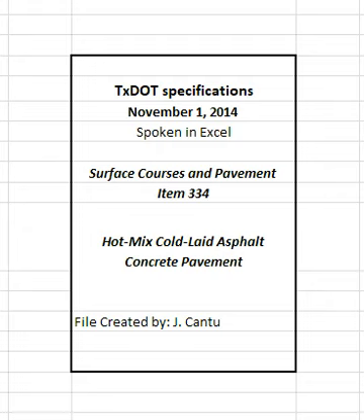Use fine aggregate, with the exception of field sand, from coarse aggregate sources that meet the requirements shown in Table 1 unless otherwise approved. Test the stockpile if 10% or more of the stockpile is retained on the number 4 sieve, and verify that it meets the requirements in Table 1 for crushed face count, Tex 460A, and flat and elongated particles, Tex 280F. Table 1.